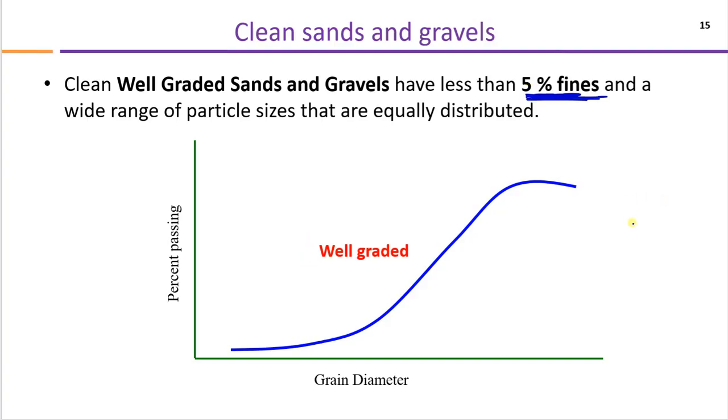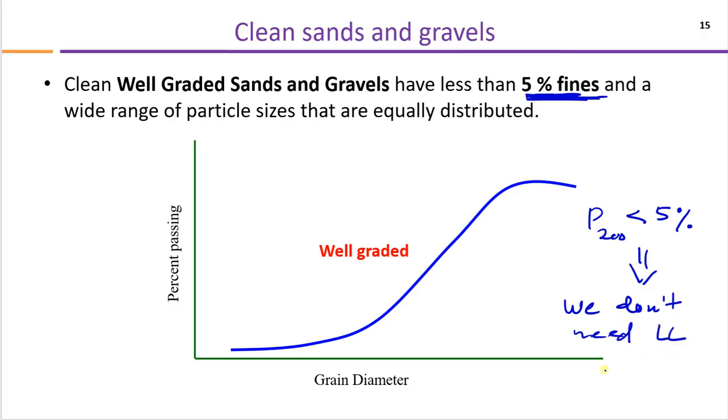And when passing number 200 is less than 5%, we don't need liquid limit and plastic limit. We cannot perform the liquid limit and plastic limit test.